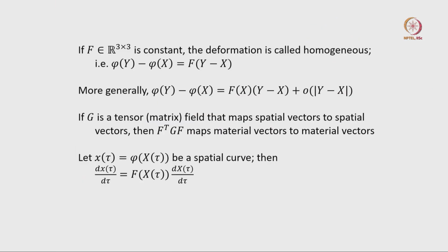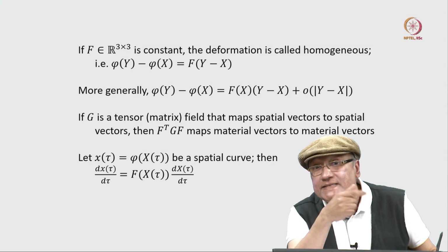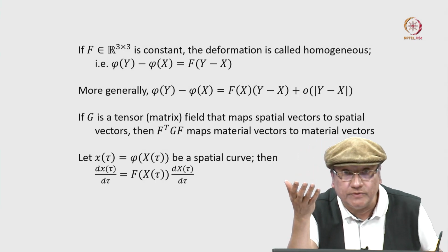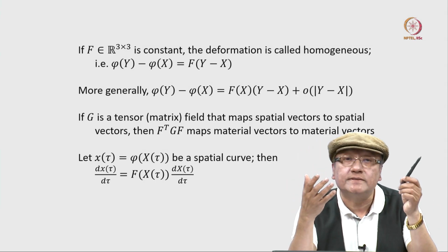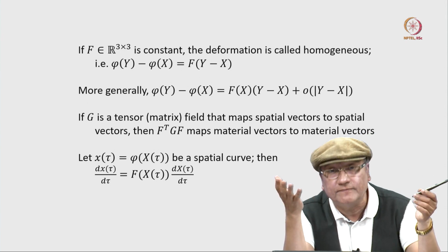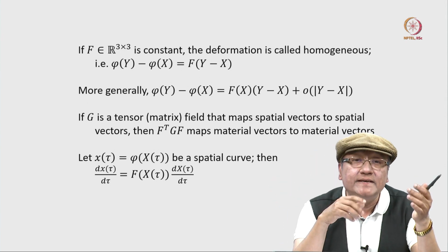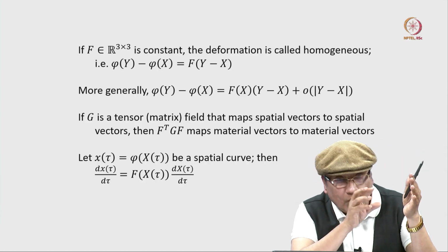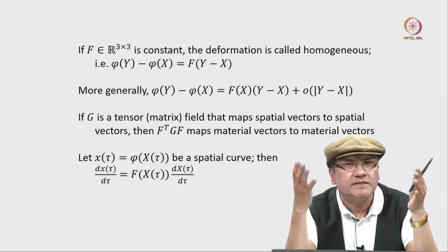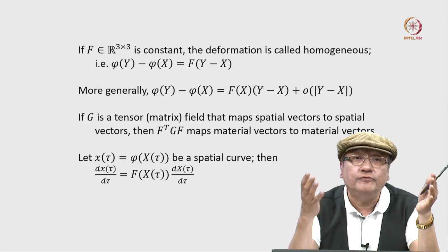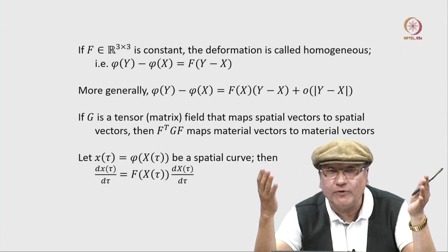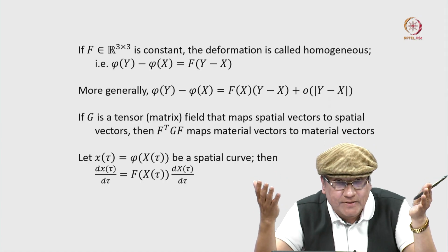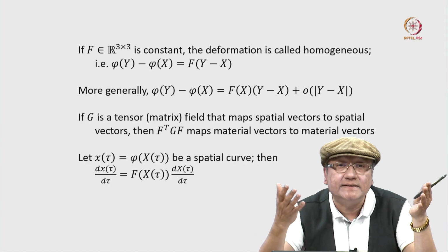So deformation is not the main thing, it is the deformation gradient that is the main thing, because it is related to those PDEs that we will be defining soon to describe the rules of motion of solids. The PDEs work only in the tangent space. All the quantities in the PDEs are tangent space objects. They have no finiteness associated with them. For example, dy by dx, when you write it, is basically a tangent space object.